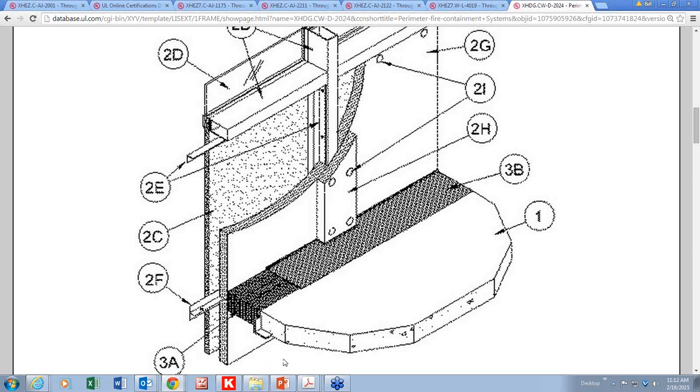It doesn't measure what happens if the glass breaks out down below at 3 feet, comes out of the assembly, and then breaks the glass at the level above it and hops into the building at that point. This is called a leapfrog type assembly, technical term obviously, where the fire laps out the outside of the building, breaks the glass, and comes back in, catches the drapes as well.